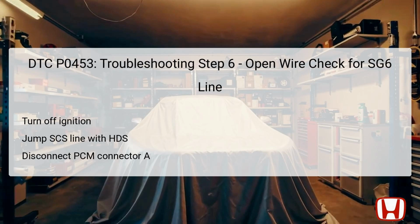DTCs. Similar to the previous step, this phase checks the integrity of the SG6 line, which is associated with the FTP sensor's blue wire. Firstly, with ignition off, you create a connection using the HDS to simulate active conditions in the circuit. Disconnect the PCM connector A, terminal 28, which is linked to the SG6 line, and connect it to the vehicle's ground via a jumper wire.